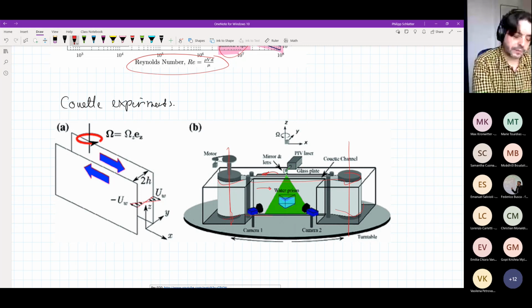And then you can do observations of this. So you can put a prism here, and then you can look in with two cameras. The reason why you need to have a prism is that the refraction of the light beams is such that the camera here looks at an orthogonal plane, and then everything inside is the same fluid, so that there is no refraction at the interfaces, because otherwise you would not know what the angles are. So you can then do observations on that. So there is a clear way of how you could build such a couette flow experiment.